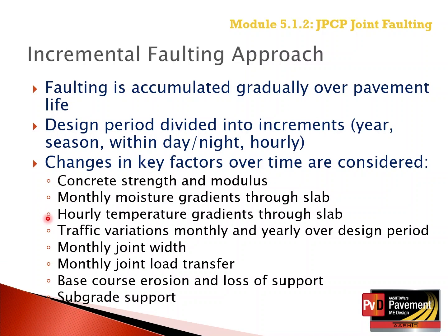hourly temperature gradients through the slab, traffic variations of each axle type and load, transverse joint opening or width on a monthly basis, joint load transfer on a monthly basis, base layer erosion or the loss of support, and subgrade support and erosion or loss of support.